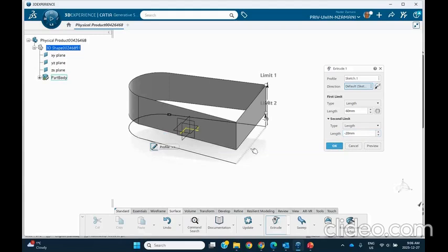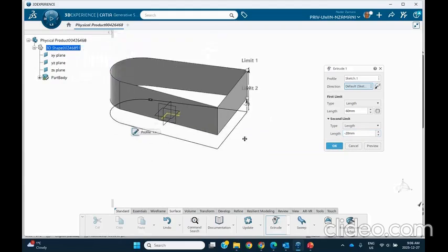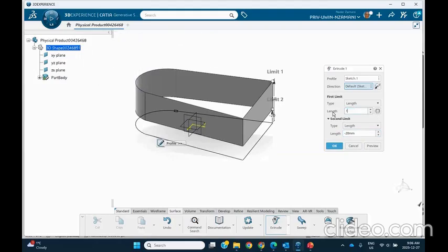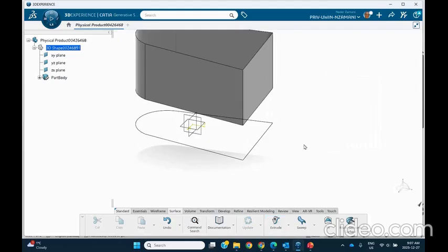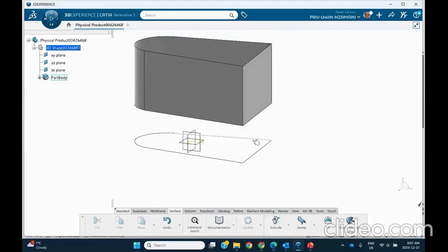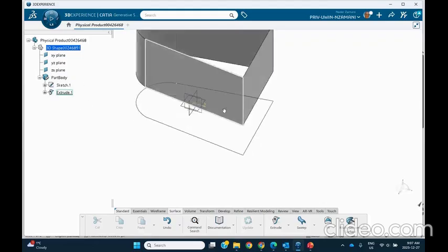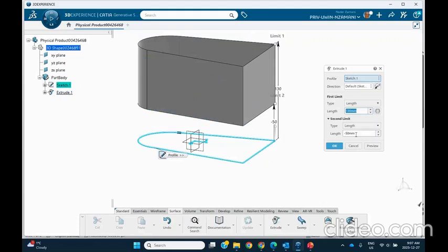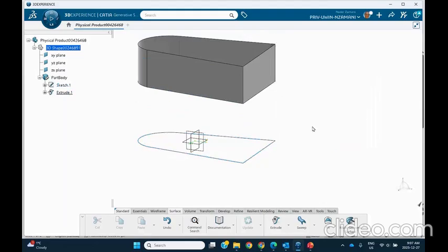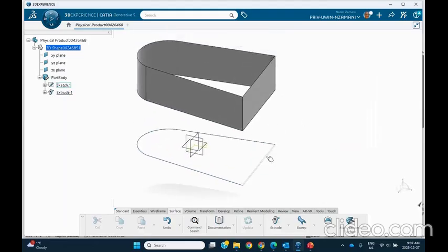Because I want you to realize that there's something down here that's a sketch. As a matter of fact, let me make this thing a 120 and make this thing minus 50, okay? Because this thing down here is a sketch, okay? I can hide it, but I want to leave it the way it is, okay? So notice that this is an open section. As a matter of fact, if we make this thing maybe minus 90, you can see it better. Yeah, good. This is my sketch, and this is the surface that I create.